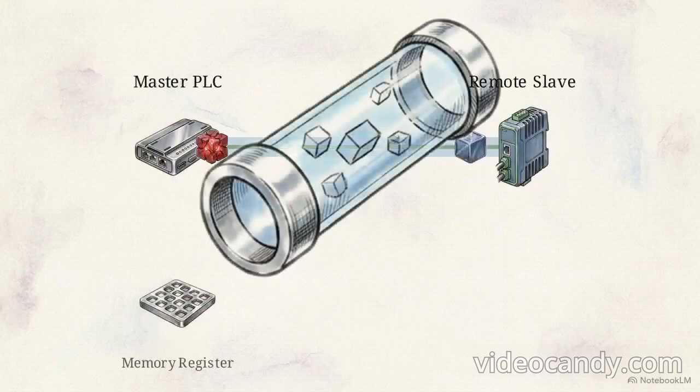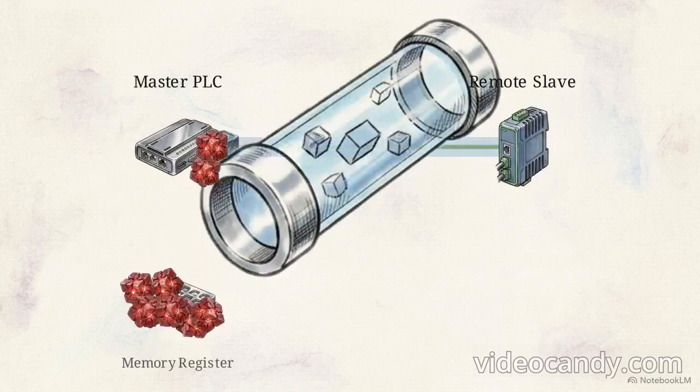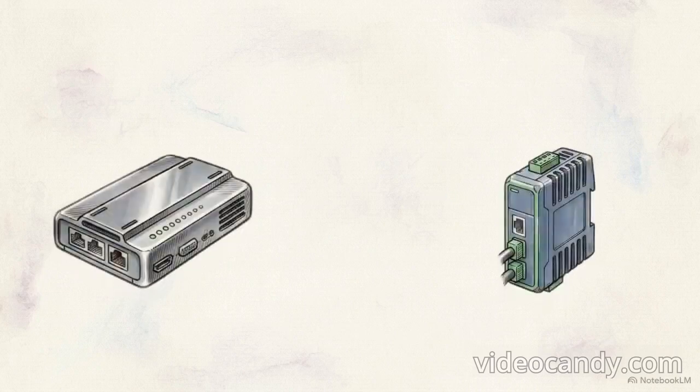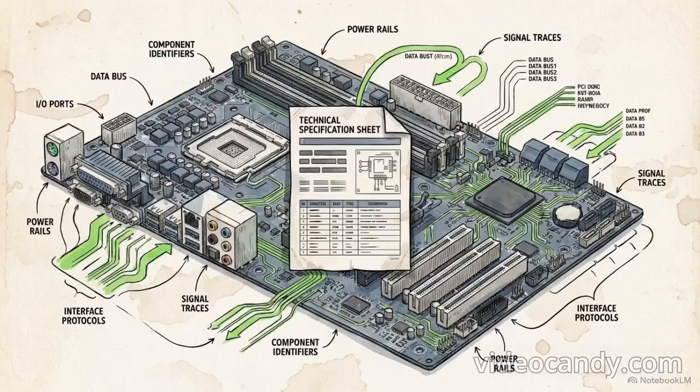This happens because standardized configuration files do an excellent job of constructing the communication pipeline between devices, but they do not translate the payload traveling inside it. Solving these discrepancies requires moving past the automation of the engineering tool to manually verify the network's byte-level architecture. The first step in integrating a field bus device is usually importing its general station description, or GSD file.